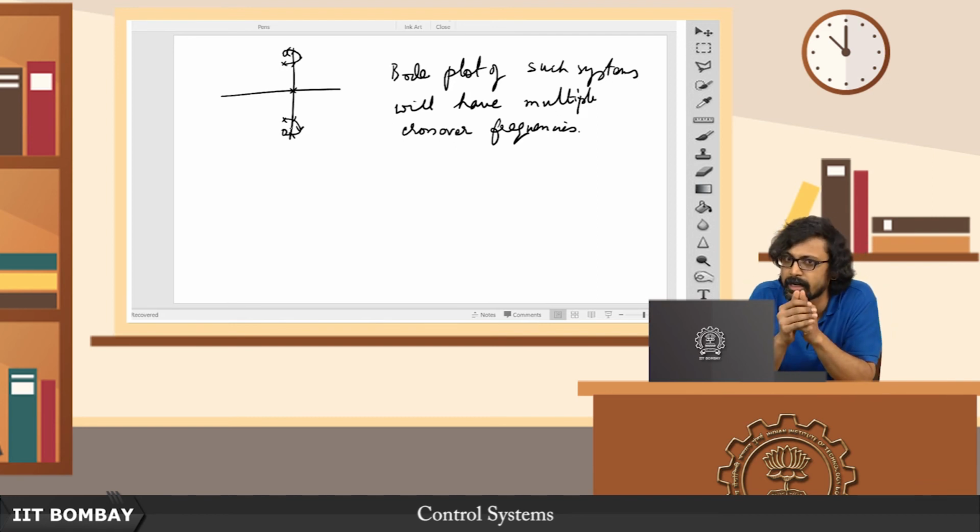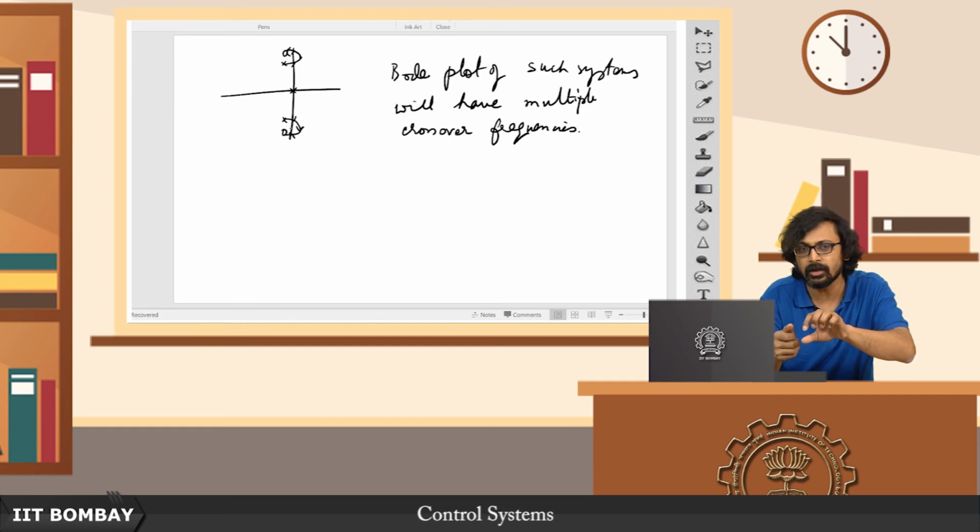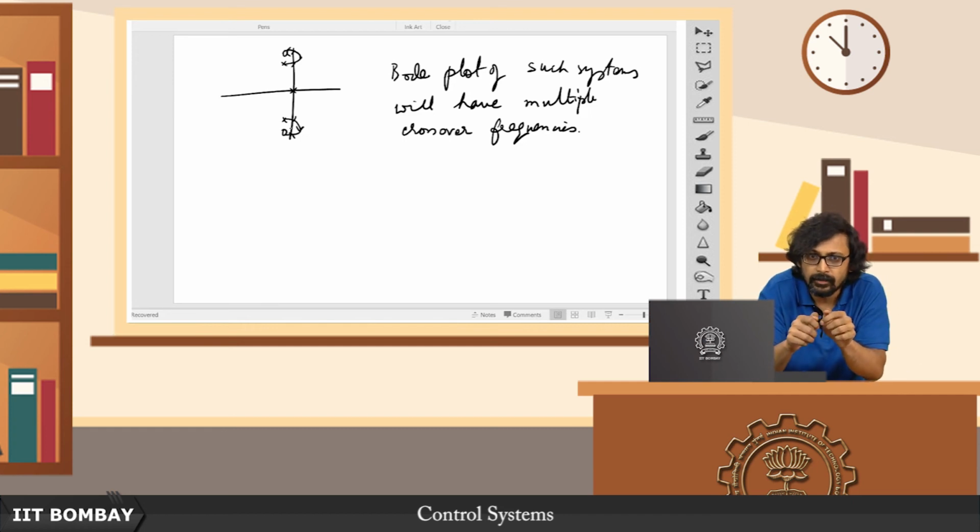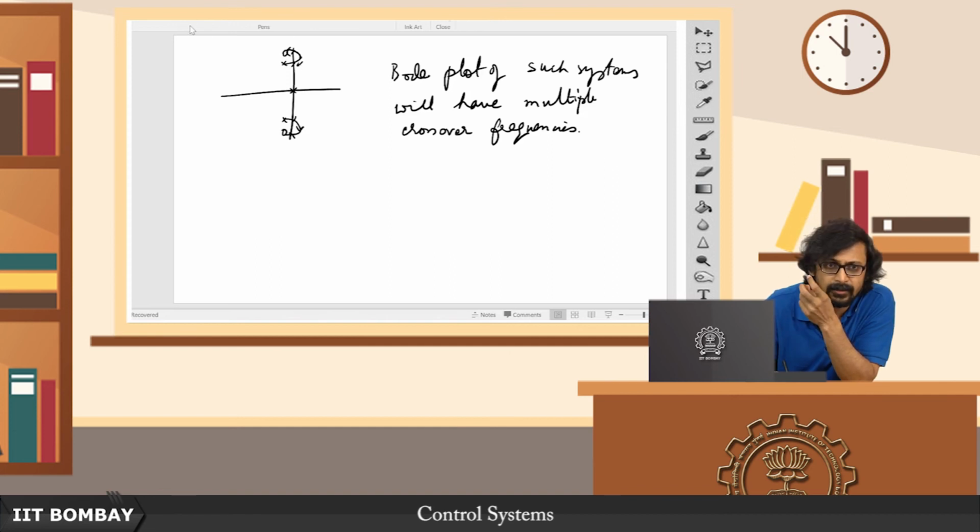Then you said, okay, this is too high, so I cannot raise it to higher values, so let me try and reduce this. So you try to reduce the gain value and it does not improve the performance much. Whereas let us say this person who tinkered with the system before you had increased the gain and left the closed loop pole here.